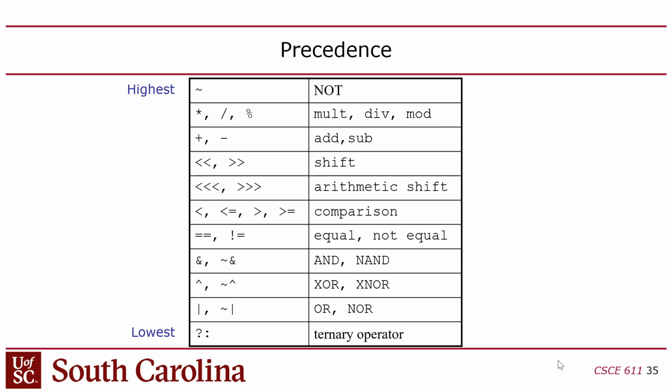Now these are interesting because you pretty much will never use these in synthesizable Verilog. You might use these in test code that's part of a test bench. But if you're doing a multiplier in code that you want to put in logic, you're probably not going to rely on the synthesizer figuring out how to implement that multiply, because there's a lot of ways you can build a multiplier, and there's a lot of trade-offs you can make in a multiplier design.